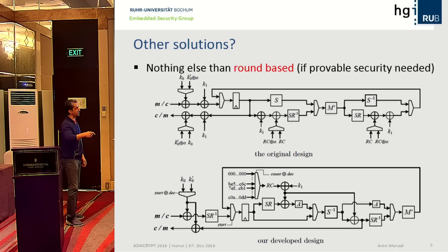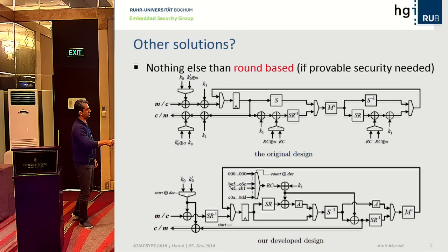And we have observed that the Sbox and Sbox inverse are actually affine equivalent in PRINCE, and then you can have just one instance of them, doesn't matter whether Sbox or Sbox inverse. We checked that Sbox inverse was a bit more optimized than Sbox, and then with two other affine functions, if you go this way, you implement the Sbox. If you go this way, you implement the Sbox inverse.